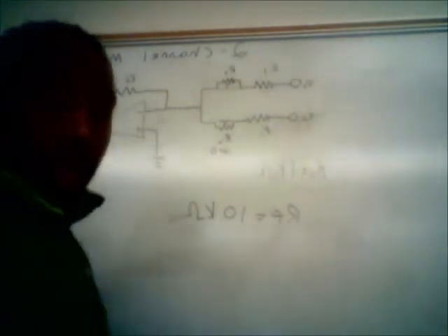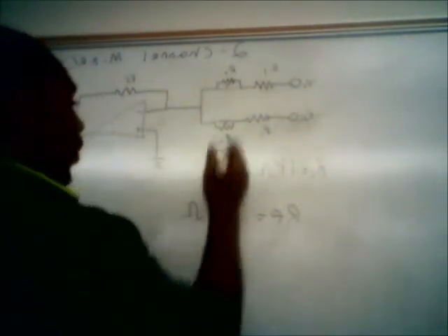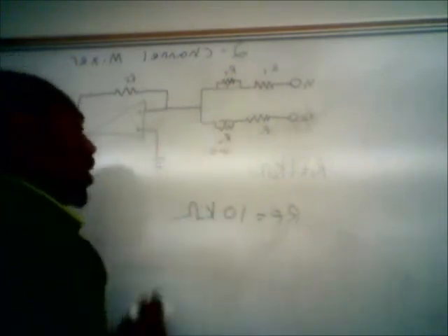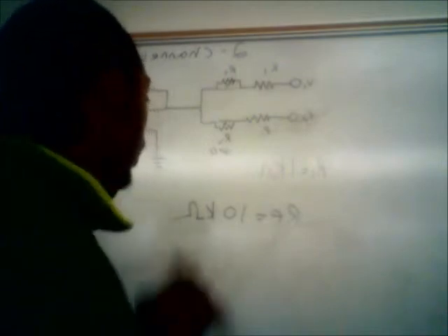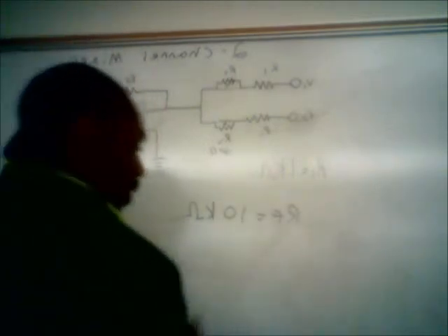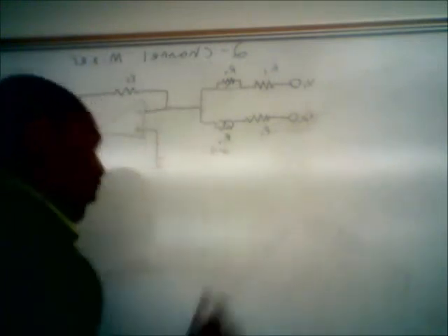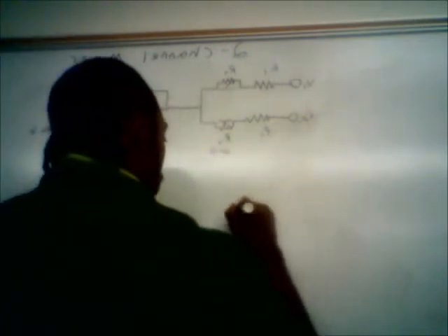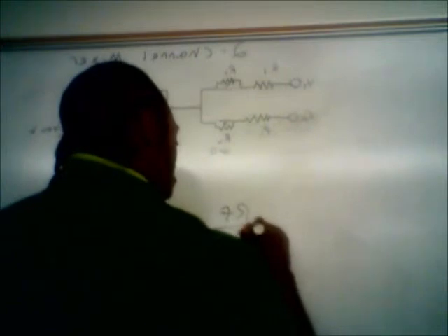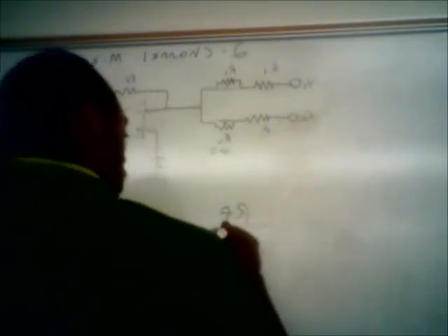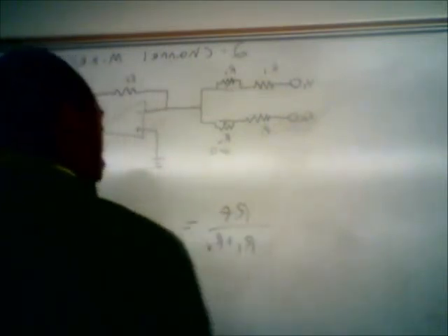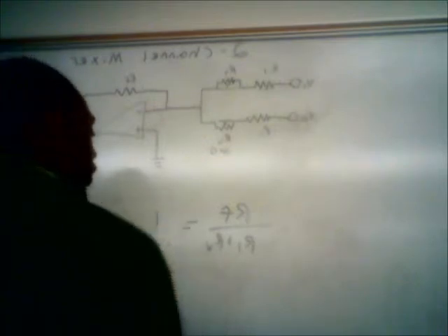All right. So now we can find a good value for the potentiometer RV by looking at the case where our gain is the smallest, and so 0.1. So we have the equation here, RF over R1 plus RV equals 0.1.